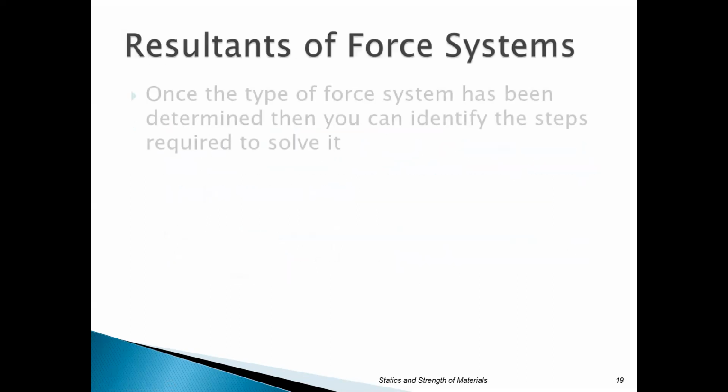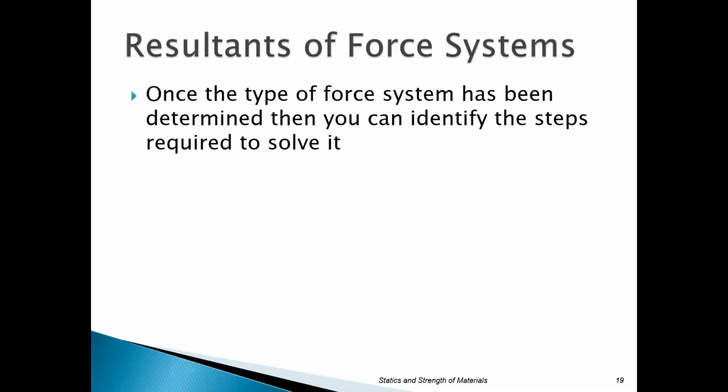All right, so let's start to consider some things. Once you've determined what type of force system you have, then you can determine how you're going to solve it. The first thing you have to do is determine if it's coplanar or non-coplanar, and we already said everything's going to be coplanar. So the next step is to say, okay, is it non-concurrent, is it concurrent, is it parallel? Once we know that, it takes us down the path of resolution.